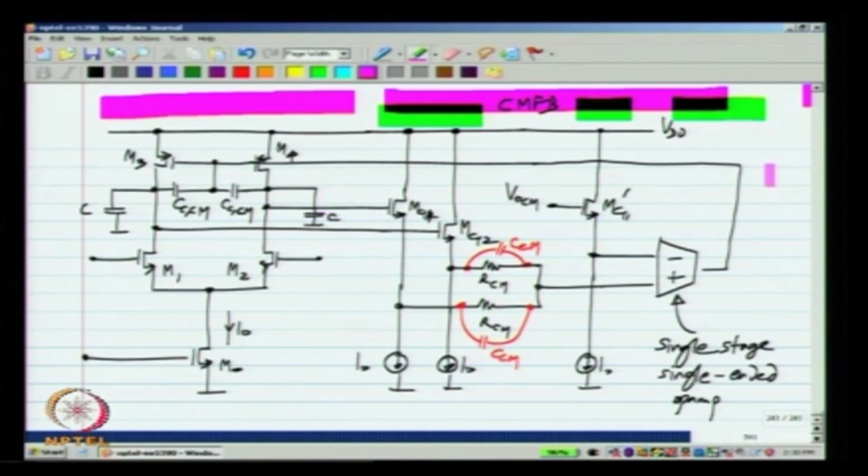We just have to live with it. Now, if you minimize the delays in other parts of the circuit, you do not need to use large capacitors here, and they can be made as small as you wish. Making them smaller will reduce the excess load on the op amp.